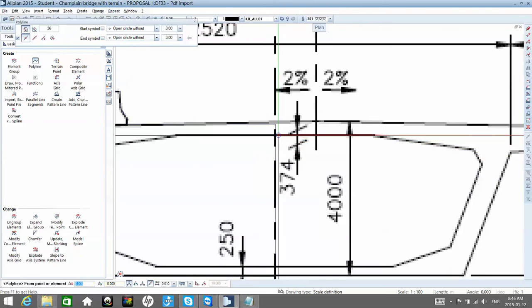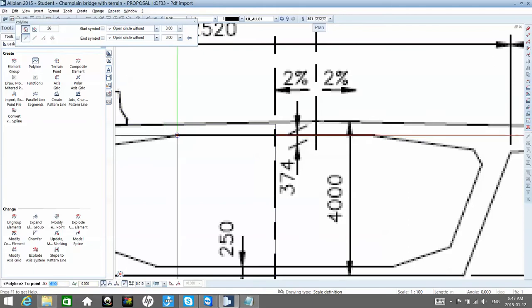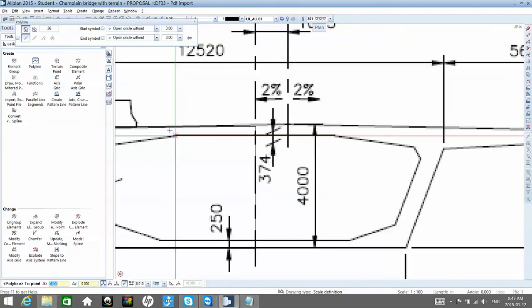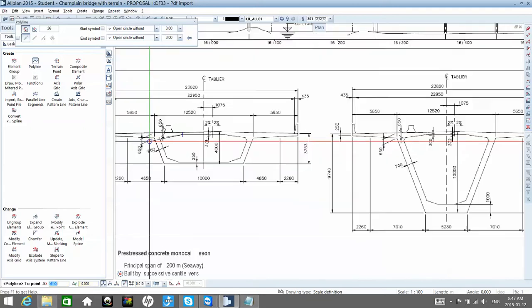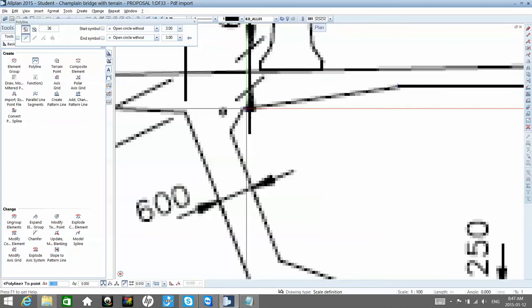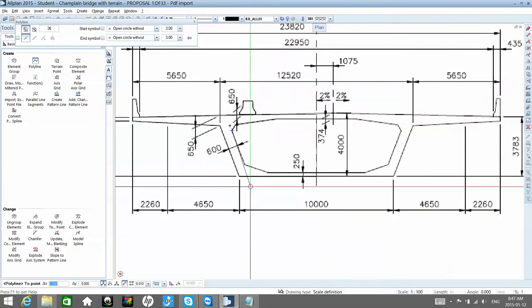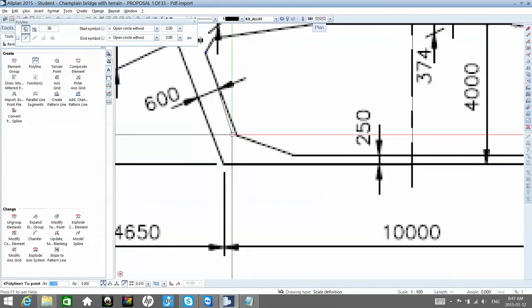So the second one we won't draw, but rather we will change the first one, because by doing it like this we will be able to maintain the number of points, because the bridge modeler can do the transitions between two cross sections as long as we have the same number of points. So we will make sure that the numbering is the same by only doing some modifications, and we won't have any surprises. So this is why I'm giving more focus to drawing the first cross section, as the other will be just a modification of the first one.